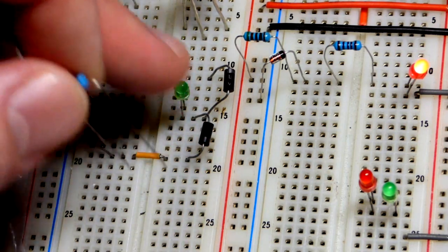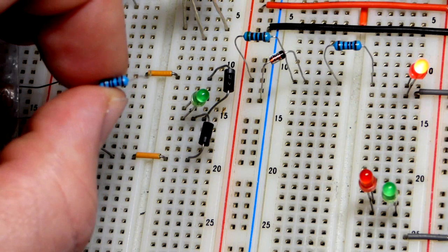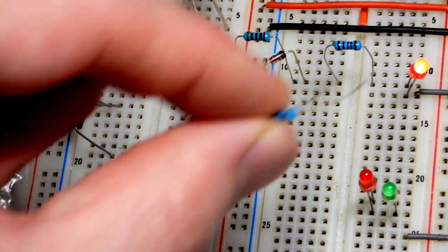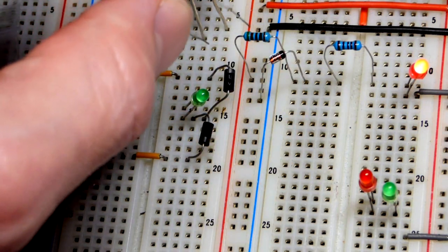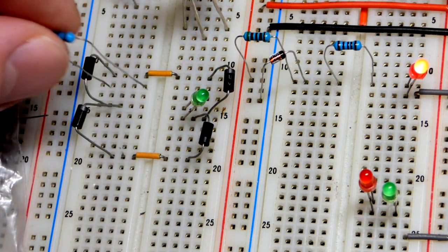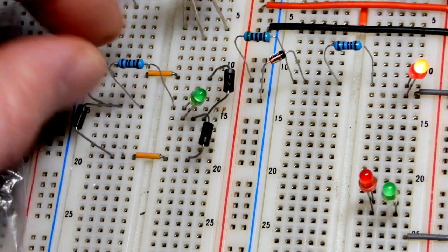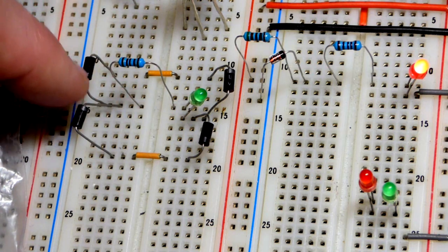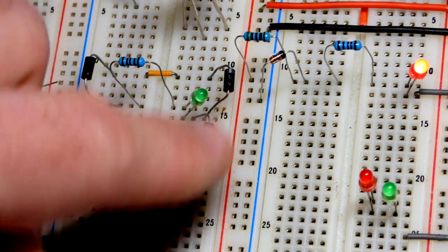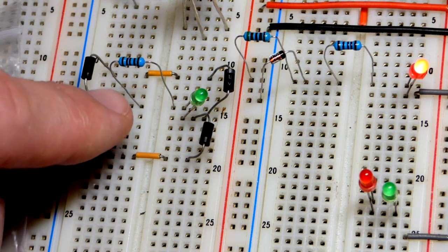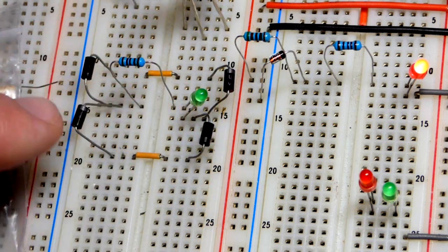The resistor here, it's a 1 kilo ohm resistor. I'm using 1 kilo ohm resistors for everything except this, which is a 510 ohm resistor, in case I forget to mention the values again. But in any case, that goes to where these two diodes are. So we already talked about how these both head towards negative no matter what. And they block positive from coming into it.